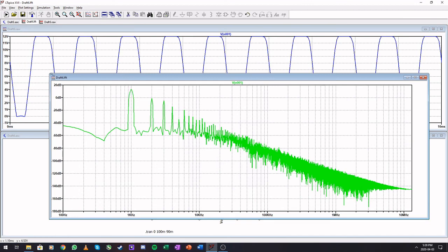The signal is much larger, but it's not a 10 volt signal, so this is smaller, but you can see harmonics that are popping up here. Okay, if you look at the block wave, this is the typical kind of signal that you should be seeing. So these points can be used in a total harmonic distortion analysis, and this signal is very distorted, so the percentage for the THD would be very high.